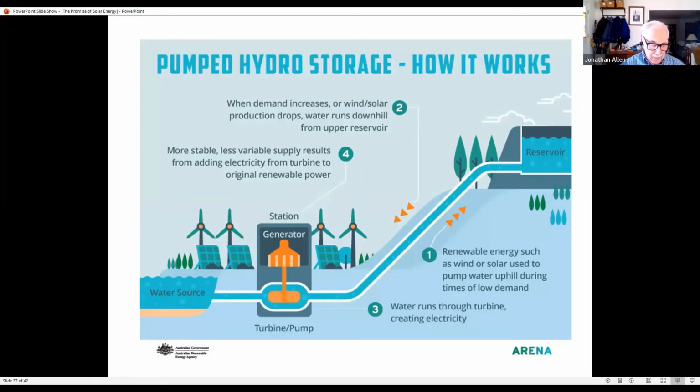Batteries. Batteries are an obvious medium, and as mentioned earlier, are already dominant in small and off-grid installations, but they can become quite costly at utility scale. In evaluating a battery type, one must also consider its lifetime, both in years and in the number of charge-discharge cycles it can endure before it craps out or loses capacity. At the moment, lithium-ion batteries appear quite promising and have round-trip efficiencies that range between 85 and 95%.